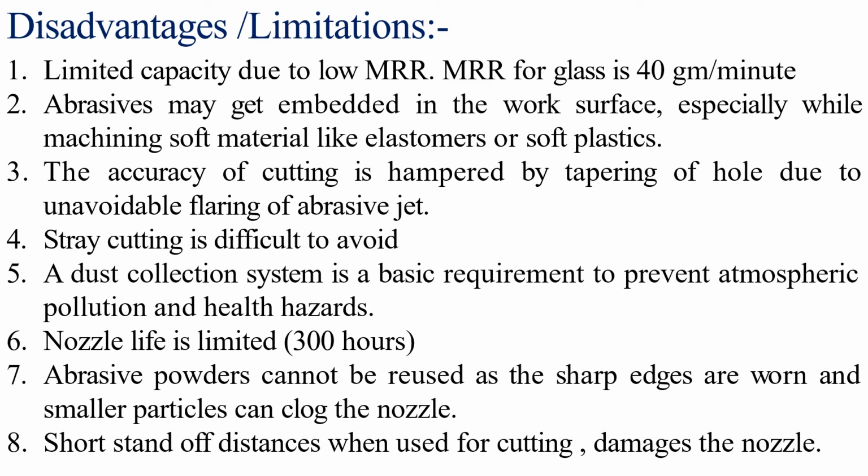Disadvantages or limitations: limited capacity due to low material removal rate. The material removal rate for glass is 40 gram per minute. Abrasive may get embedded in the work surface, especially while machining soft materials like elastomers and soft plastics. The accuracy of cutting is hampered by the tapering of the hole due to the unavoidable flaring of the abrasive jet. Stray cutting is difficult to avoid.